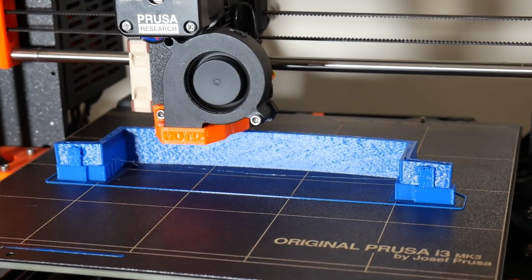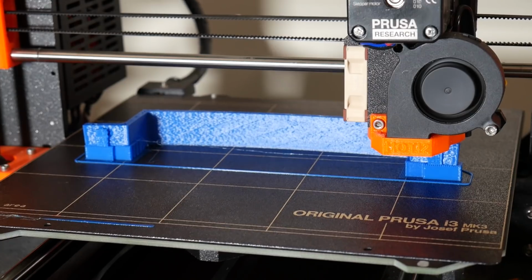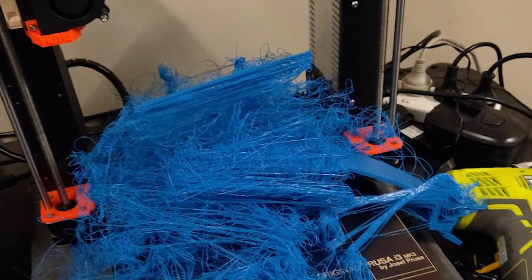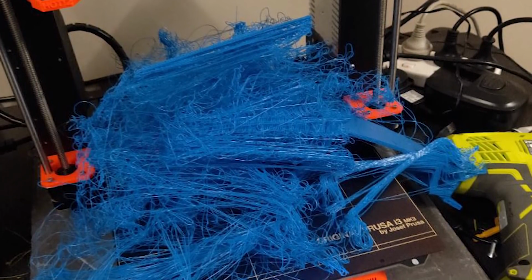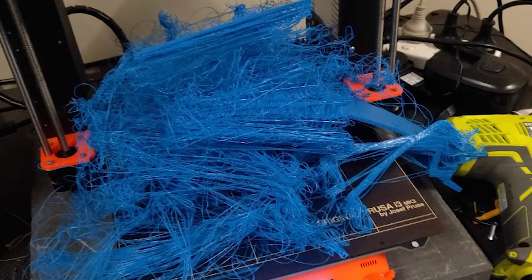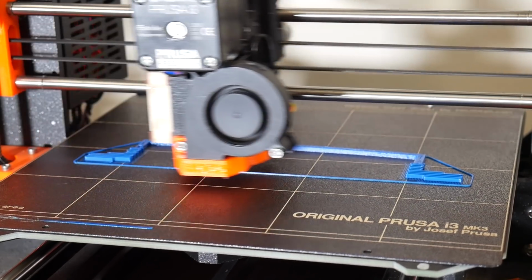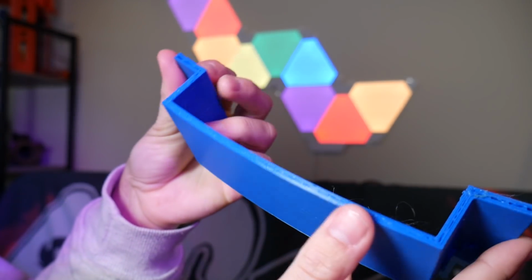In the end, I only printed one half of the battery holder for the electric longboard, and this print failed, actually. I came back to a big pile of plastic, and I wasn't exactly sure why, but then I realized that we didn't actually have much bed adhesion, and it's been very cold. It's pretty much the heart of winter here in Australia. Although we don't get negative degrees, the workshop definitely gets cold at night, and I think it just wasn't enough bed adhesion.